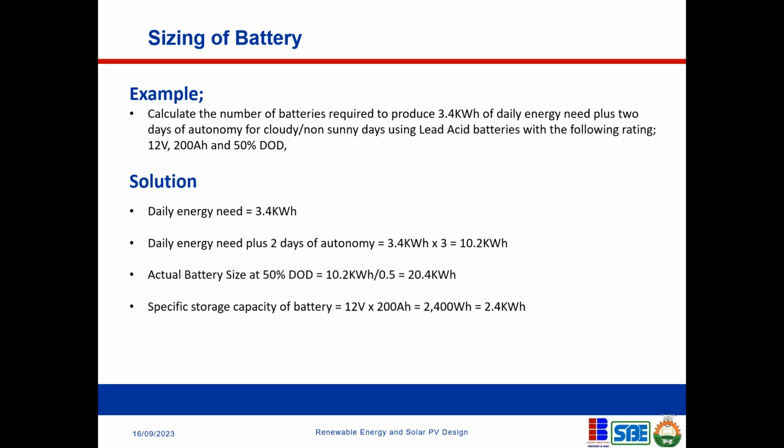Okay, no. When you're calculating for your battery, as long as it is in kilowatts, you don't need the power factor. You only need the power factor when it is in kVA, which we now call apparent power. But when it is real power or active power, you don't need the power factor.